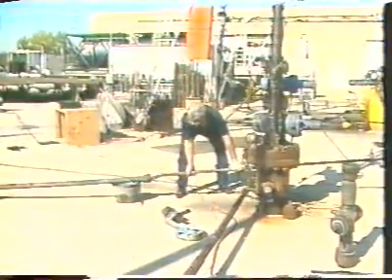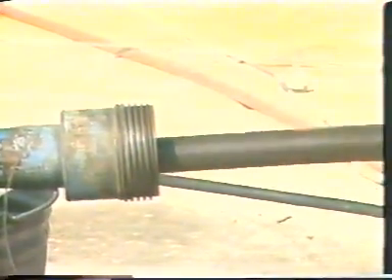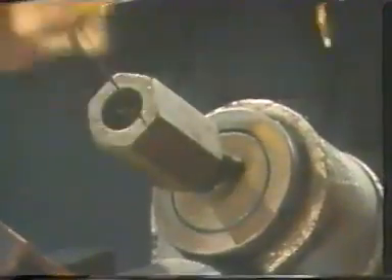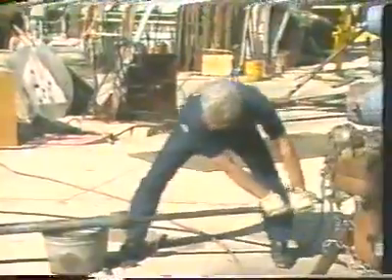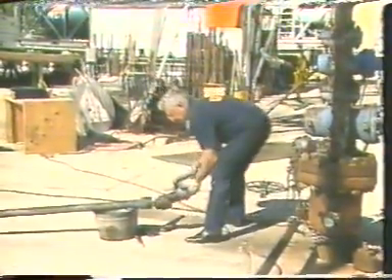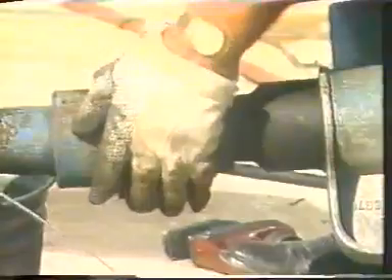The tool string is assembled and slid into the top of the lubricator, leaving about 1 foot sticking out of the top of the lubricator. The wireline is threaded through the stuffing box and attached to the wireline socket by tying a knot in the wireline. The wireline socket is screwed onto the tool string, and the completed tool string is pushed completely into the lubricator. Now the stuffing box can be attached to the top of the lubricator sections to complete the lubricator assembly. The stuffing box seals off around the wireline to contain the well pressure in the lubricator stack.